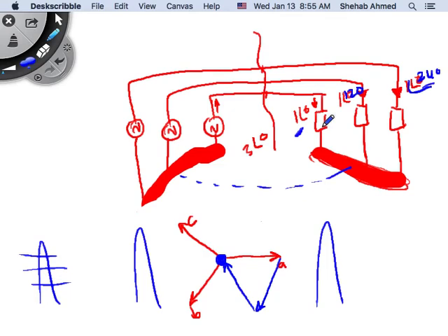So in distribution systems, it's very difficult. That's why distribution is an art, right? Designing a distribution system, you have to know who's living here, how they consume power, what time of day they consume power, etc. They will have to know this is a university building and approximately how many students. The more you know about the load, the better you can distribute the power. If you don't know too much, you will distribute garbage. Not garbage, but I'm saying you will have a significant unbalance and big neutral currents, right?